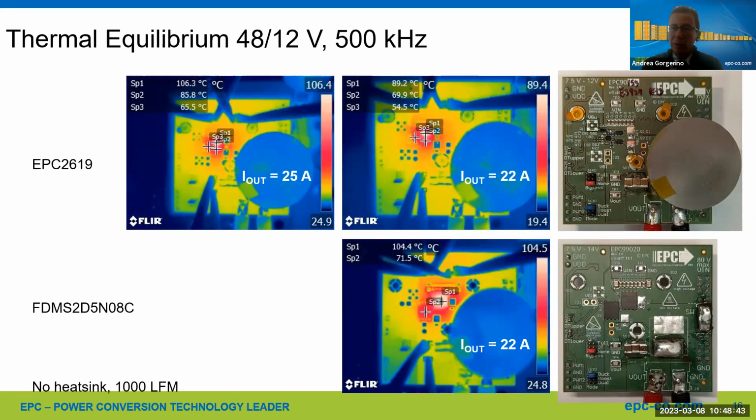It's not hard to make a good layout. It's just that if you don't think about it and you use the layout you were used to before, you will get high parasitics when you start switching fast, which will create ringing all over the place. So I really encourage everybody to look at our website. We have some very clear guidelines. We also have all of the reference designs. They all use a similar way to make these layouts. But the layout part, you just have to implement it in a way that really takes care of the things I mentioned. And then after that, it's pretty straightforward.